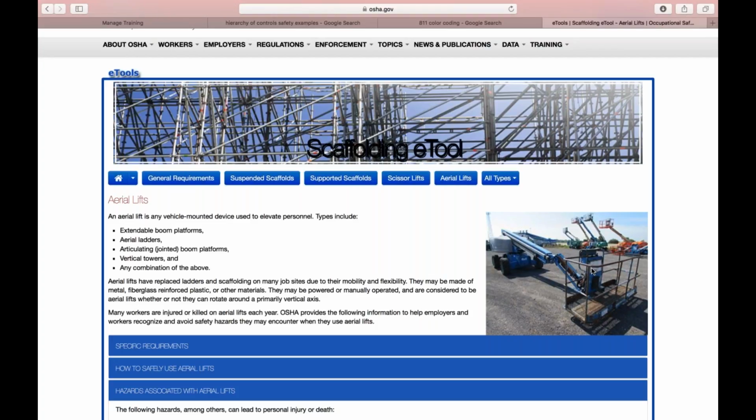Fire protection and prevention as well. Is there going to be an adequate number of active fire hydrants on the work site? If not, are we bringing in pump trucks? How many fire extinguishers do we have? Do we have any type of firefighting foam capabilities? So we take all that into consideration. We're going to list the number, type, size, and locations of all fire extinguishers. Do we have any standpipe systems?